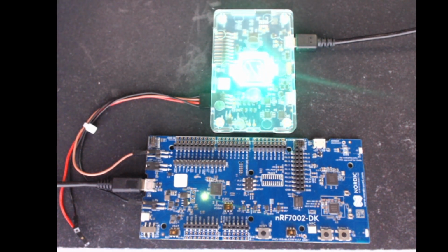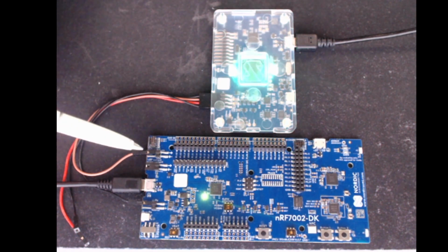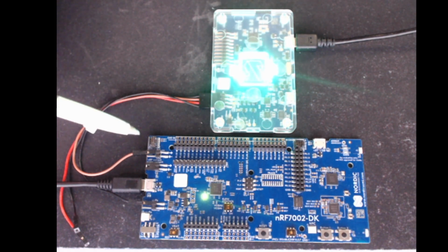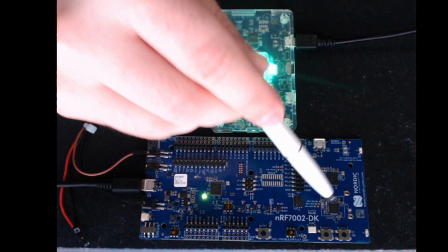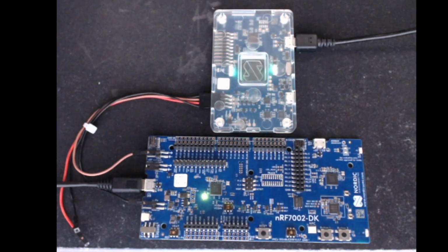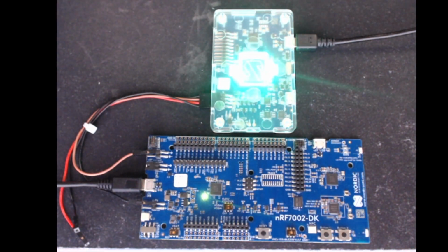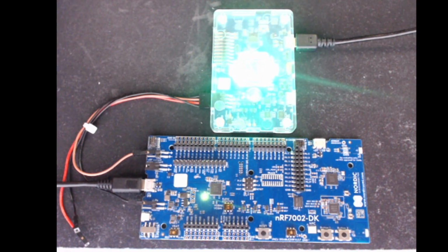Then on the Power Profiler application, which controls the PPK2, we're going to configure it as a source meter, supplying 3.6 volts into the board. And this connection here is actually going to supply the Wi-Fi circuitry, so the nRF70 device, which is on this board directly. And with that, we can measure the current consumption that the PPK2 is supplying to the board.